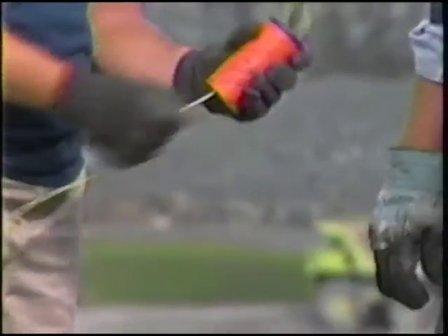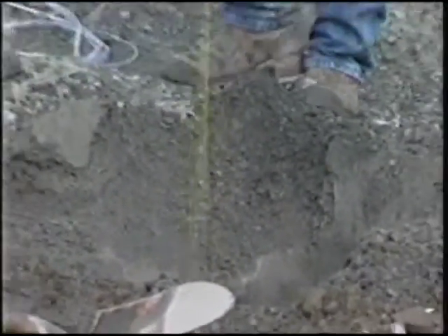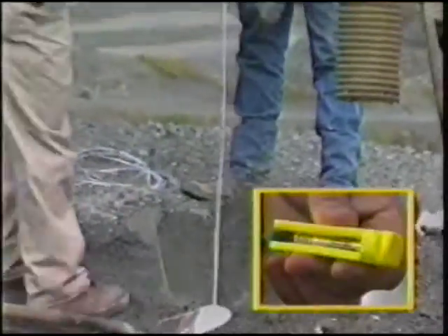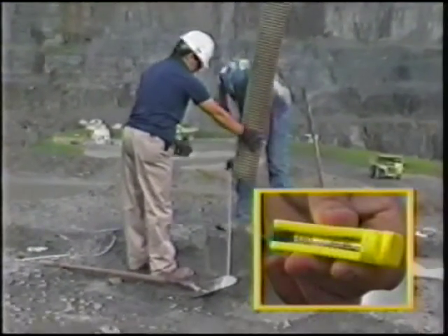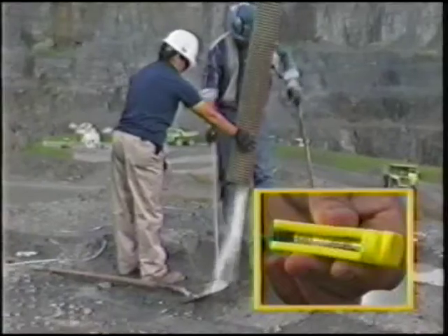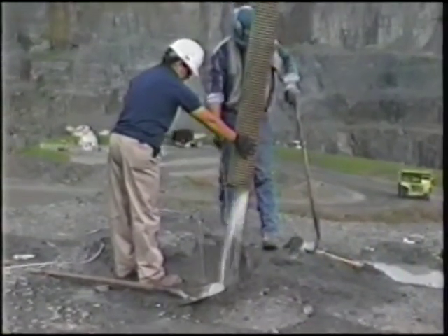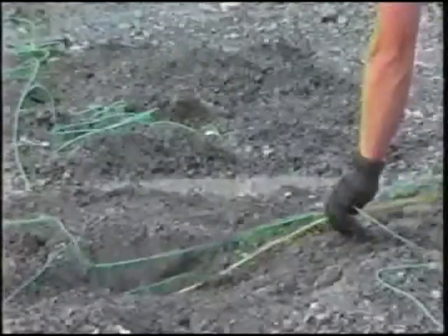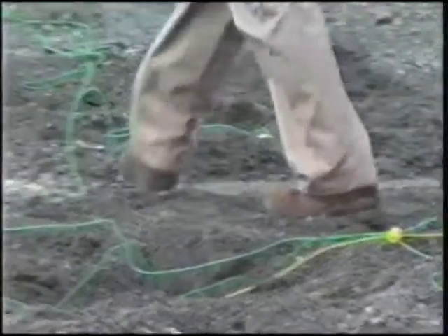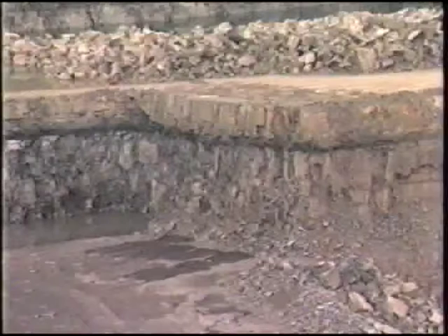After drilling has been completed, the holes are then loaded with explosives and blasting caps. The caps are designed so that all the explosives are not detonated simultaneously. They have built-in delays to facilitate timing a blast to reduce ground vibration and noise. Once the explosives have been prepared and loaded, the blast shot is ready to be activated.